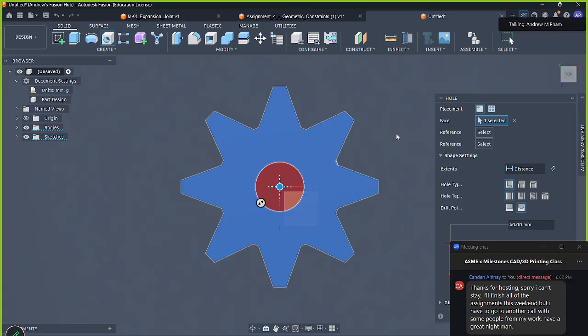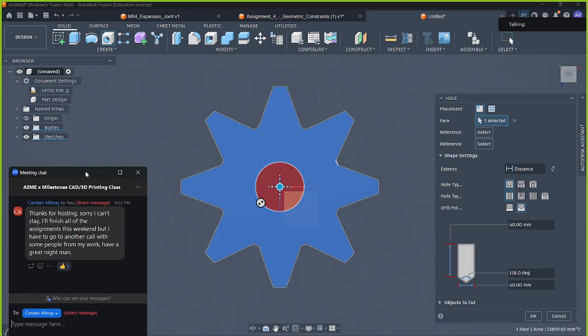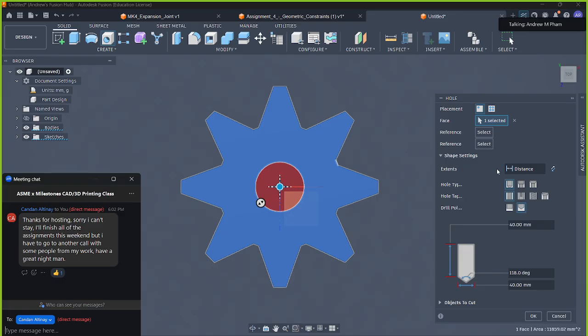All right, so it's going to be here. But you can see here, can I move this? You can see here that there's a lot more information than before, right? So I think before I had like a 30 millimeter diameter hole or something, right? So, it would be 30, but there's a bunch of other options, right? You can even specify the angle of the drill bit, like the taper angle.